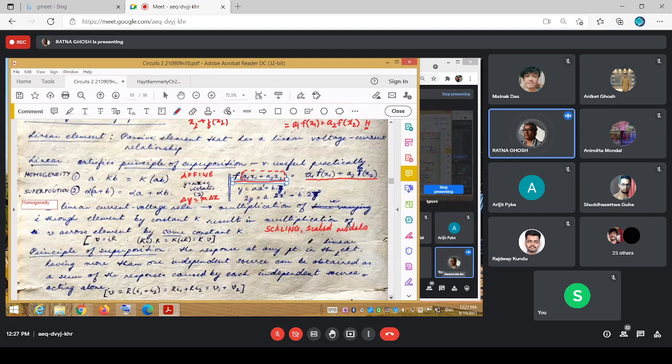Okay. What does that mean? That supposing you want to make some simulation, rather some hardware model of a large plant or something. The typical process for designing a large plant would be to first simulate it. Software simulation would be done. Then part by part you would put in small hardware into that, and check that. That is called hardware in loop simulation.